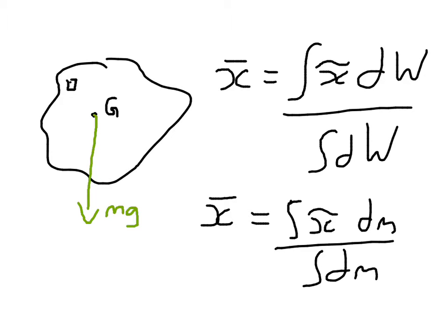If you look at slide 9 of the lecture notes, there are some common centroid positions for some common shapes. So, for instance, a rectangle. The centroid is halfway in the height and halfway in the width. So, x bar is going to equal width over 2.